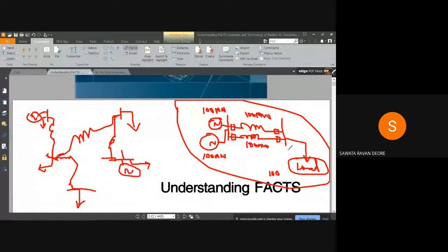Whereas that 33 kV line comes from a taluka place, where there is a 132 by 33 or 66 by 33 kV substation, and that 132 kV line is coming from the district level, where there is a substation like our Kharghar substation, where 400 by 132 or 220 stepping down is done.